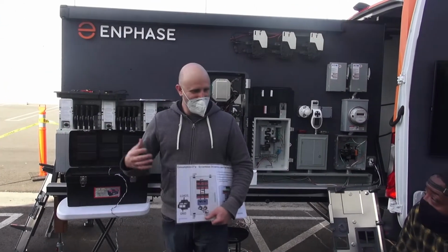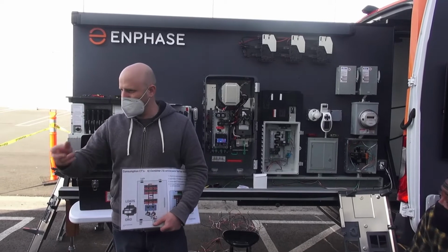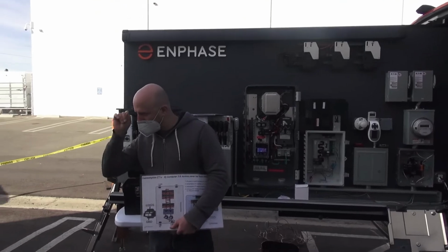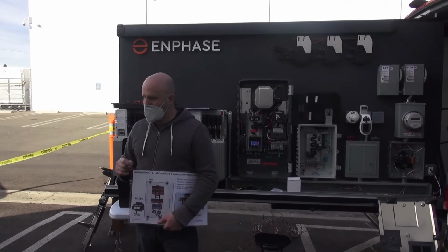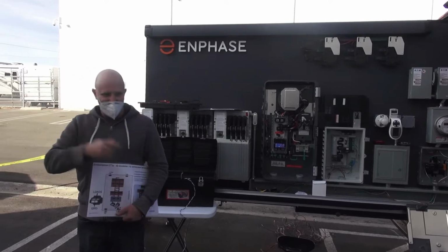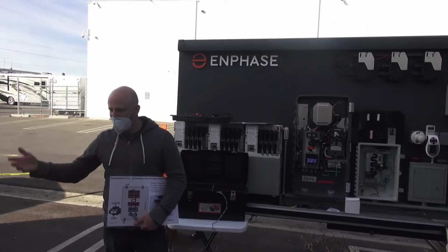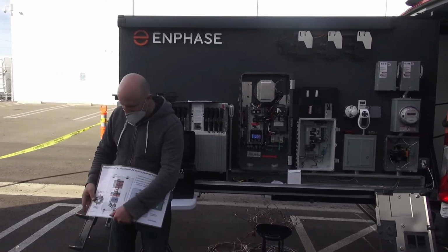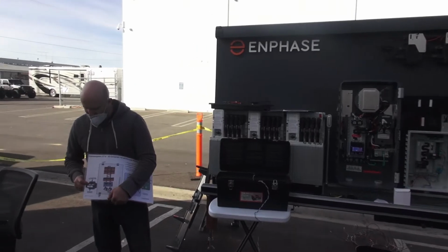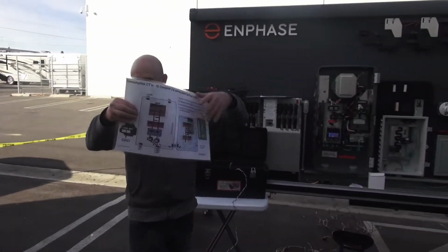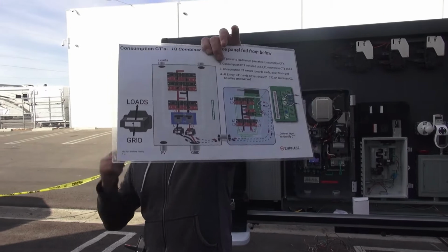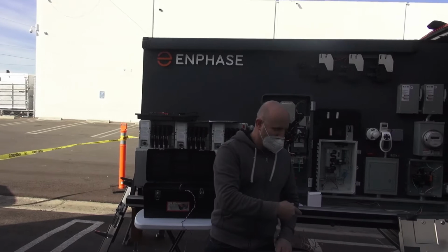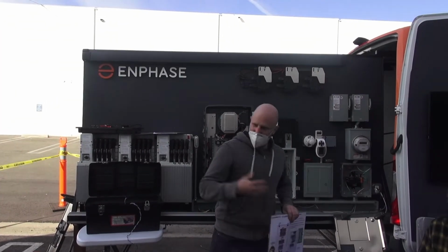So many people think it just doesn't matter. Line 1, it's 120, 120. It does matter, because we're measuring the amps and the voltage specifically on that one conductor. So just to finish it, CT2 goes on line 2. Just like before, the arrow points toward, yes, thank you.